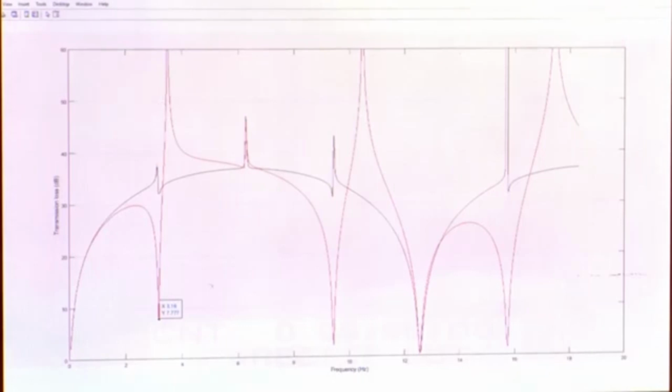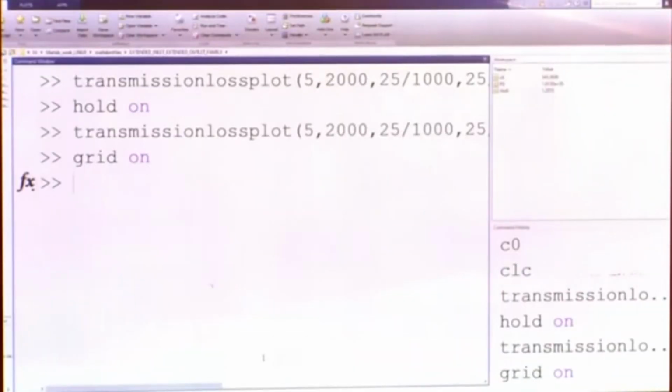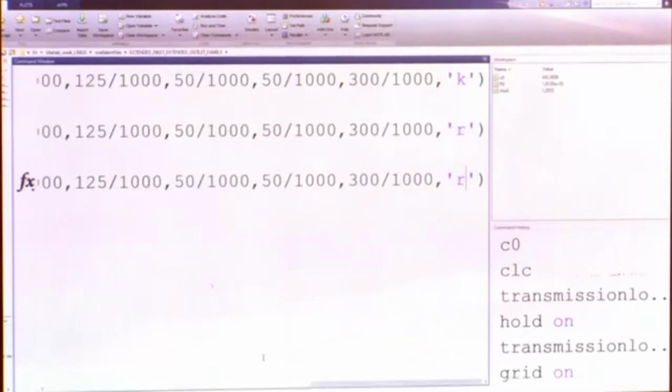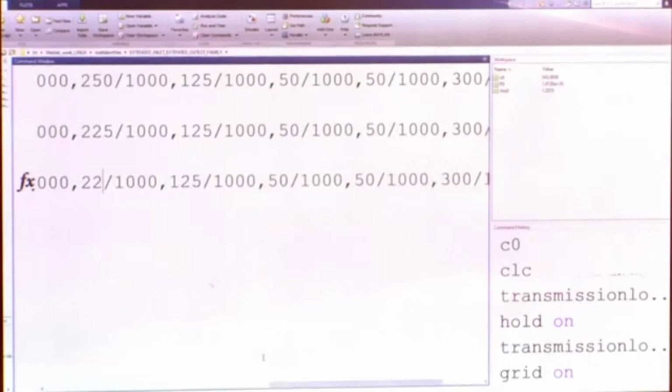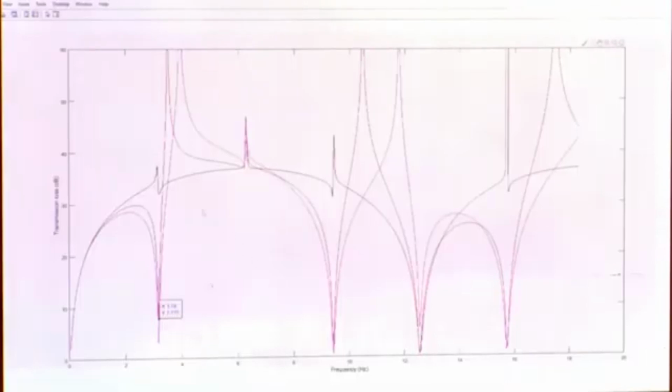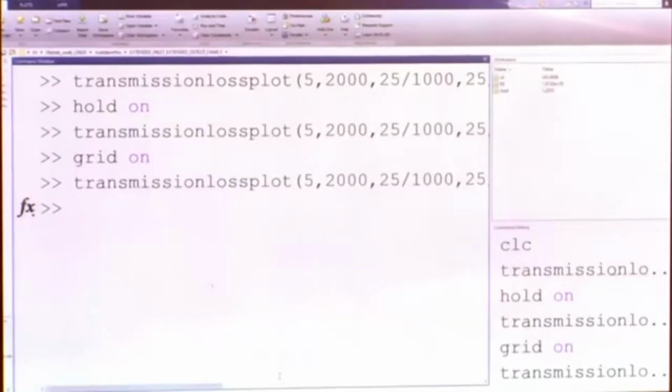This trough occurs close to 3.14, and that is because the length of the extension is less than L by 2. So, naturally, based on the plane wave limit, the frequency is pushed up. Now let us consider a couple more parametric studies at the inlet. Let us use another color. Instead of 225, let us put 200 and see how bad the results are. We still get the trough at the first actual peak, and this peak shifts towards the right because the annular cavity length is now less.